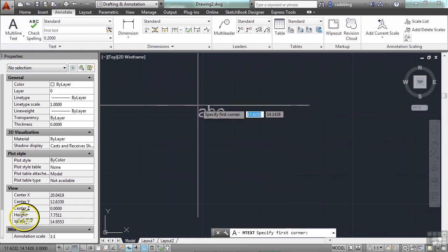When entering text, you specify opposite corners of a text bounding box. That defines the width of the paragraphs in the multi-line text object. The length of the multi-line text objects depends on the amount of text, not the length of the bounding box. So you can use grips to edit that later.